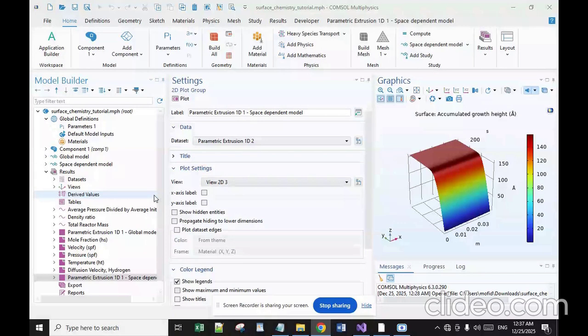Aerosol assisted CVD, in which the precursors are transported to the substrate by means of a liquid gas aerosol, which can be generated ultrasonically. This technique is suitable for use with non-volatile precursors. Direct liquid injection CVD, in which the precursors are in liquid form, liquid or solid dissolved in a convenient solvent.